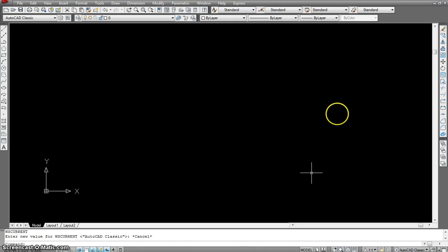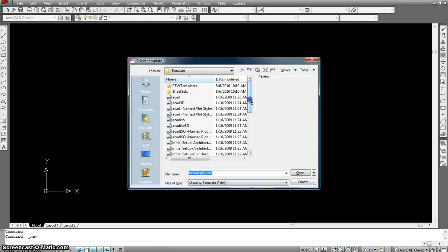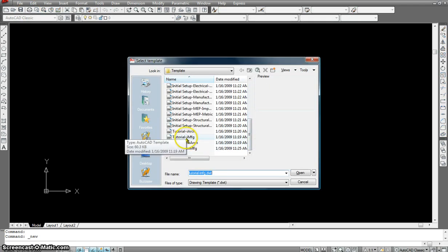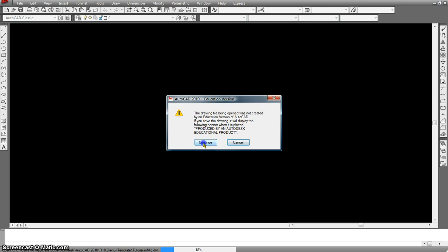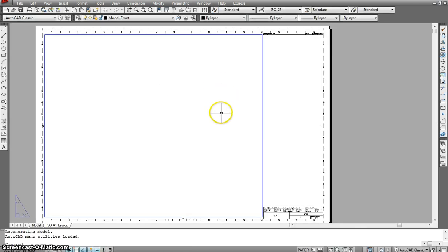We go to AutoCAD. Make sure you're using a metric template this time. So I'll go File, New. So far we have been using IMFG because that was in inches, but today we are going to use a metric manufacturing drawing. So I'm going to use that tutorial template. Hit open, continue, and now the title block looks a little different from the one before, so you know that you are in the metric template.